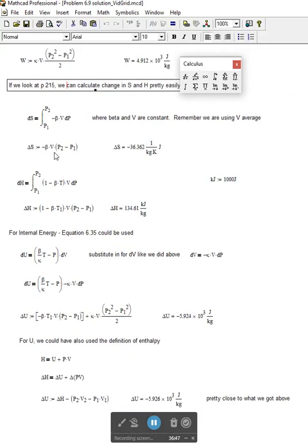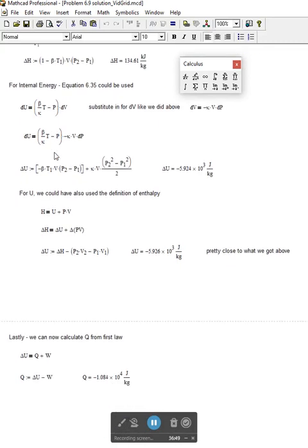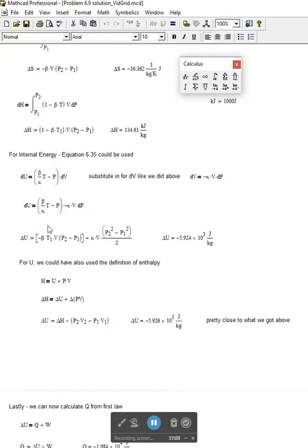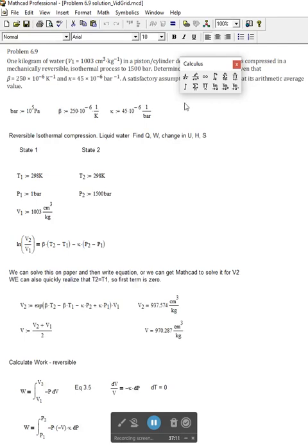One of the things you have to be aware of is that MathCAD has certain reserved things. For example, we had defined work as W, but W is also the base unit and the default unit for electrical energy, the watt. And so if I went up to the very top of this, before I've calculated any work, and I type W is equal to 1 watt.